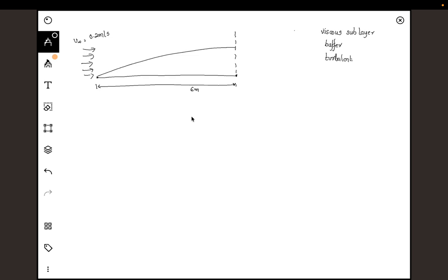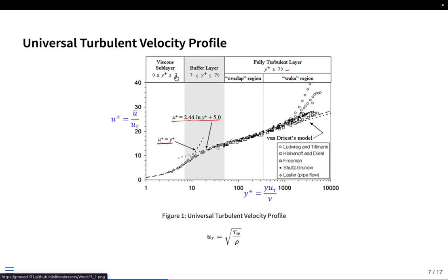So if you have the value of y plus, this is something that is referring to this particular range. Let's say y plus is greater than 70. These are the different typical values. We'll just use the values that have been there previously. Yes, so it is 7 to 70. So I'll just use a little higher value. We are interested in measuring the velocity inside the sublayer.